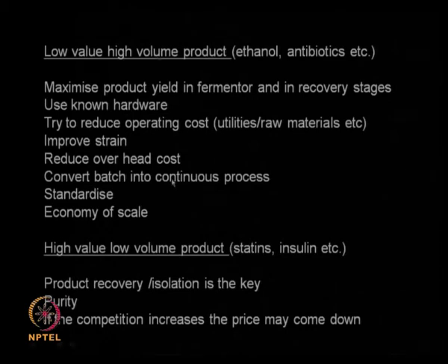See whether you can convert a batch process into a continuous process, because if you can do it continuously, then you will be continuously manufacturing the product at the same purity and yield without disturbing any of the equipment. That is why a continuous process is very ideal for high volume or high quantity material. Standardize, keep everything standard, do not try non-standard. As I said, if you have a special shoe made for yourself, it is very expensive. If you go to Bata and buy a shoe, it is cheaper.